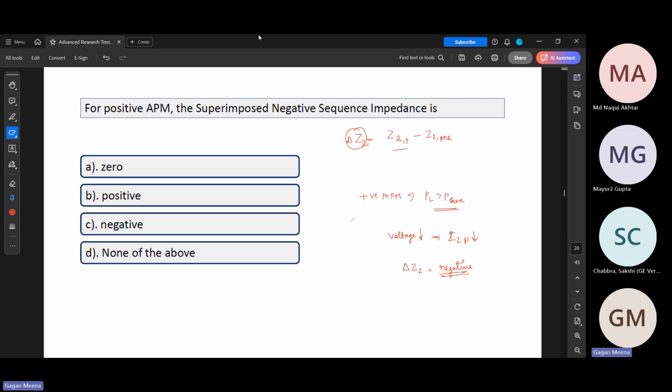Yeah, because what you're saying is correct. That decoupling is there in the transmission system. Although in the transmission system both P and Q and voltage and frequency are related together, the nature of the transmission system is such that we are able to decouple it. The influence of voltage on active power is not that much, because of the nature of the physics itself. But in distribution systems, we cannot directly decouple them.